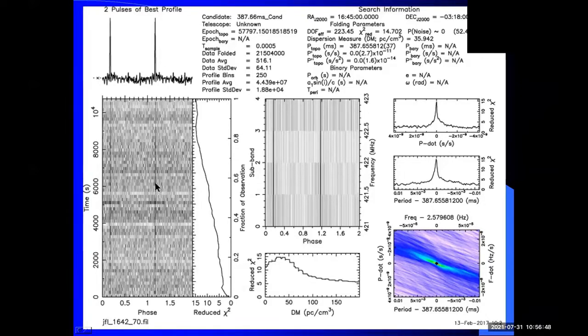They're just about appearing. With 64 sections, the apparent signal-to-noise ratio is reduced by the square root of 64, which is 8. So we're seeing effectively in each one of these blocks a signal-to-noise ratio that averages 35 divided by 8, which is just over 4 to 1. And so it's just peaking above the noise level.